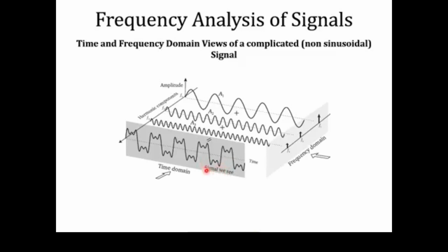So by looking at the time domain representations of signal at the input and output of a system, we cannot tell what particular frequencies have been retained by our system and which frequencies are rejected by our system. So if you will take the signals spectrum both at the input and output side, then we can conclude what frequencies are retained by our system and what frequencies are rejected by our system.